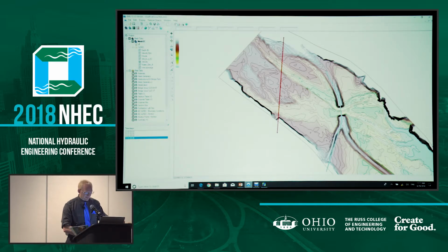The next one is going to be the center line. So I'm following our depth data set, kind of following the deepest parts of the channel, but I am on a touchpad, so we're not talking great accuracy here. And now we're going to create the main channel bank arcs. You can define these either way you want to.